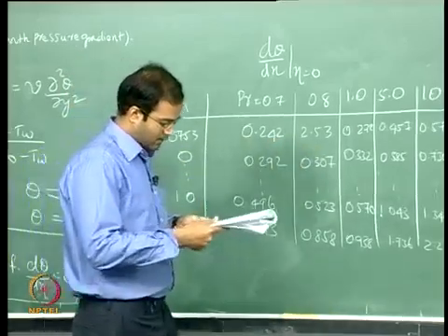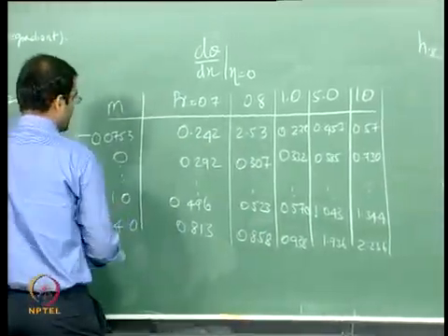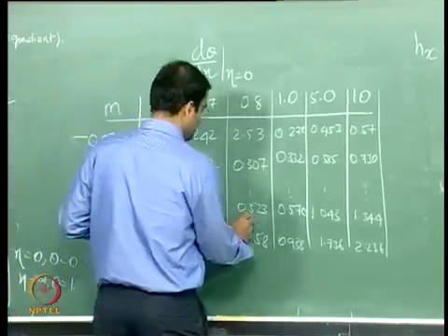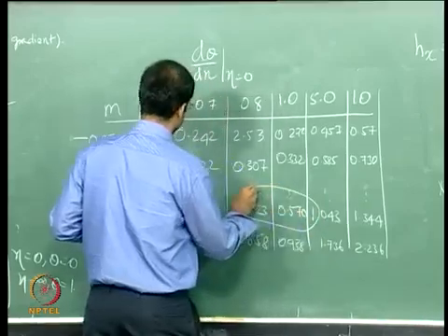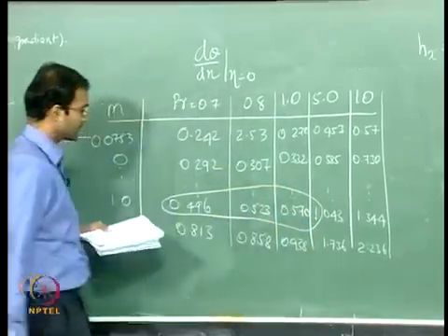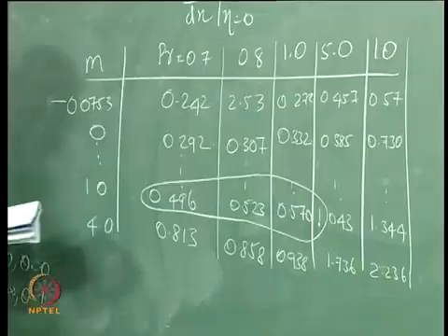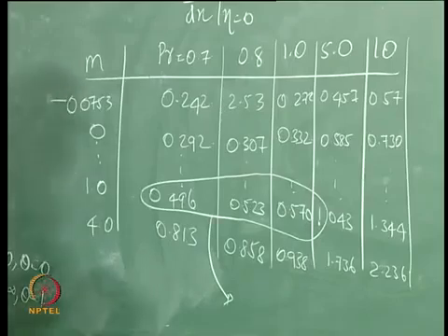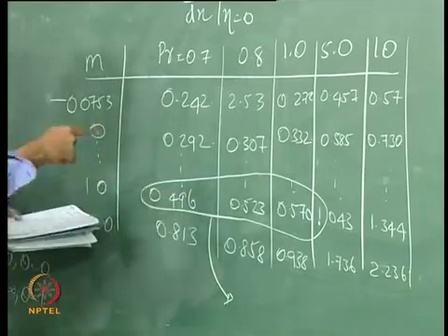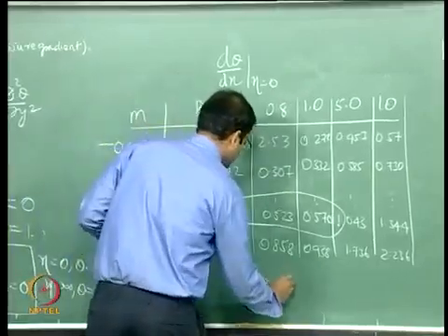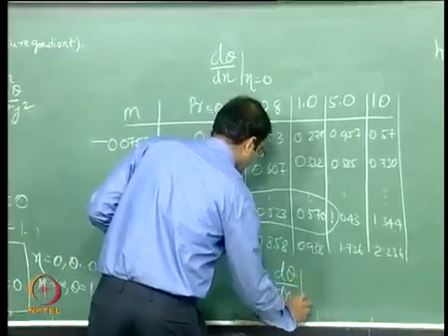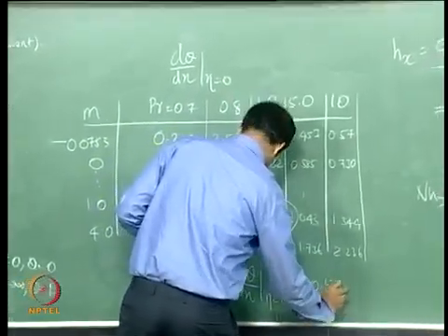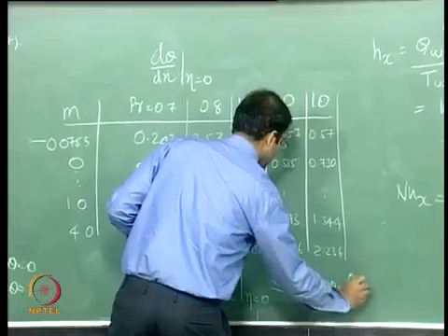Okay, now for the stagnation point flow, if you are interested in values of Prandtl number about 1, that is something in this particular region right here, you can in fact fit a curve to the values of d theta by d eta in this Prandtl number regime close to 1, and you will get a nice curve fit of this particular form, which is 0.57 times Prandtl number to the power 0.4.